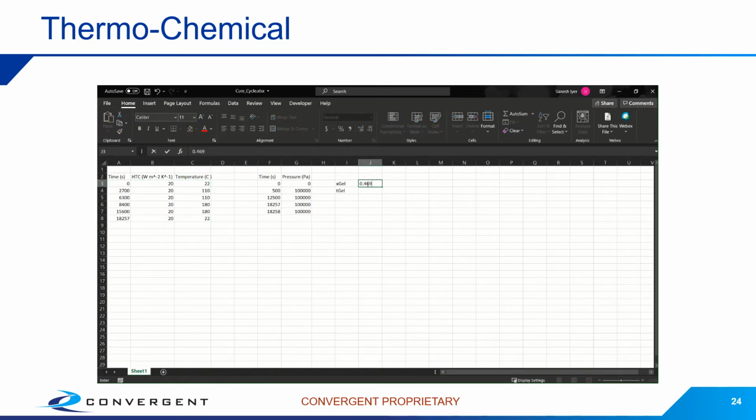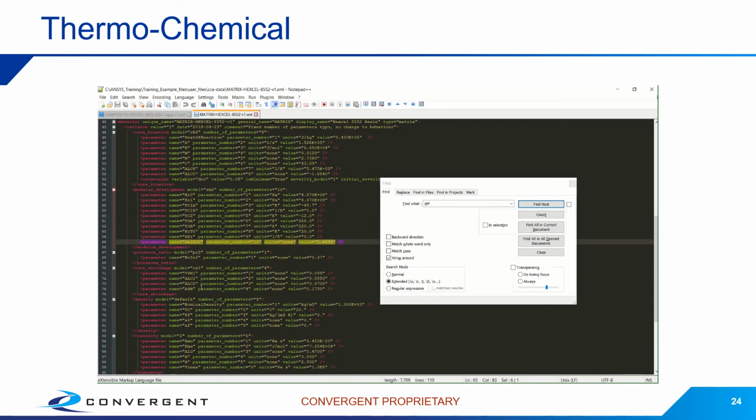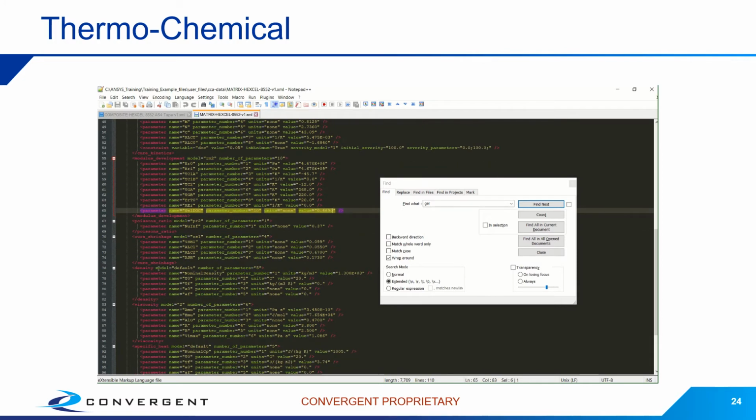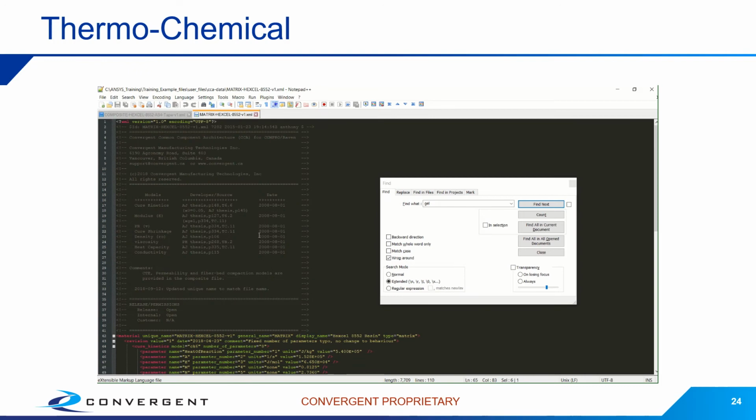And so these CCA material data files contain all of the different models. So in the case of this matrix, we have cure kinetics, modulus, Poisson's ratio, cure shrinkage, et cetera. So I'm going to go back to Mechanical. Simulation is done. So that was quite quick.